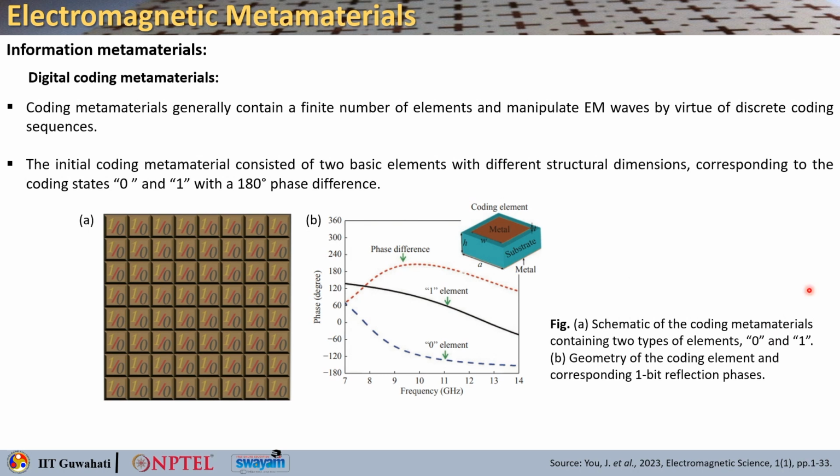These patches are designed with widths of 4.8 and 3.75 millimeter, and that is where a phase difference of approximately 180 degree is obtained in the broadband.